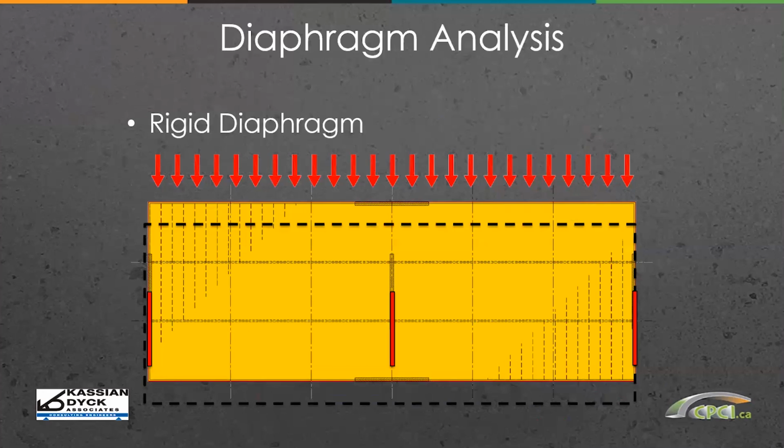So in that case, with a totally rigid diaphragm, if it's a rigid plate and it moved that whole floor system uniformly, then we know the load in each of the shear walls is equal, and we would design the diaphragm as a rigid plate, and we would undertake to design differently than if that system was a flexible beam.